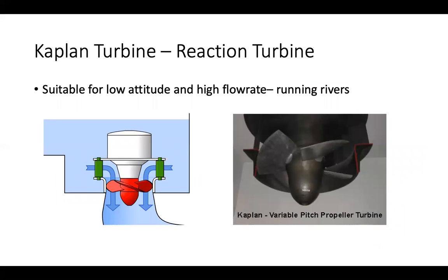Kaplan turbine. It is another type of reaction turbine and it is suitable for low altitude and high flow rate, which is in running waters or the diversion type of hydropower plant.